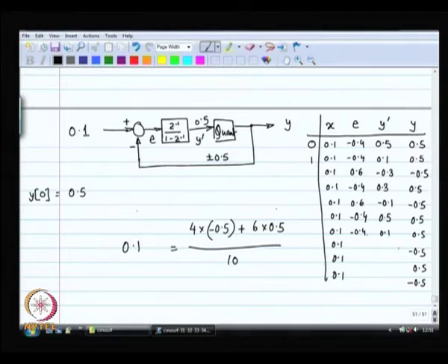The unfortunate part over here is that the cycle repeats itself. So, first of all, this is the basic sigma delta modulator. This is called a first order sigma delta modulator. The cycle is repeating itself, meaning that you are still stuck with periodicity, and as long as you are stuck with periodicity, you are going to see spurious tones at your output.